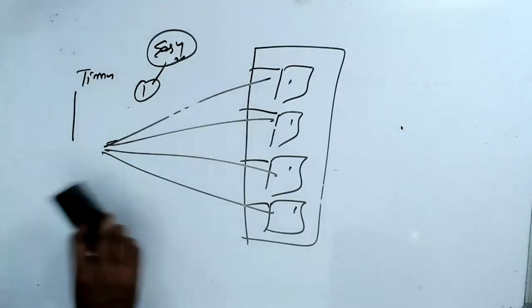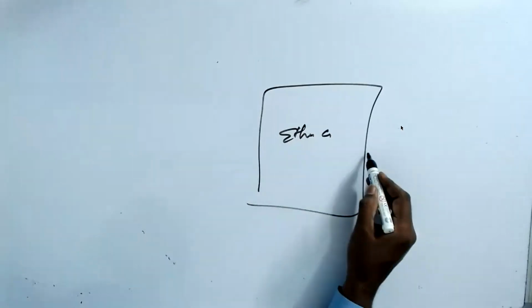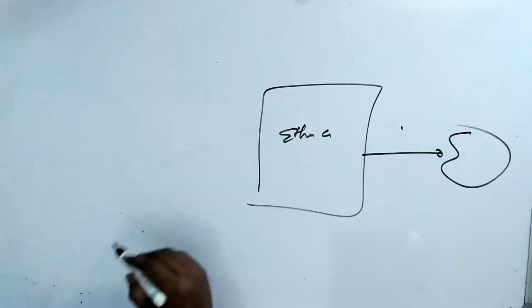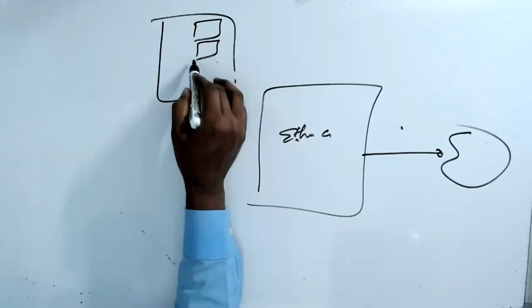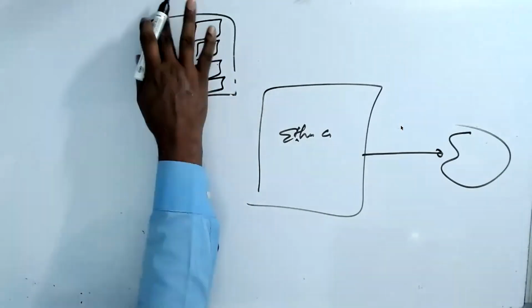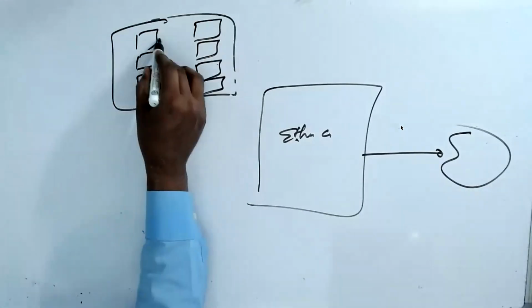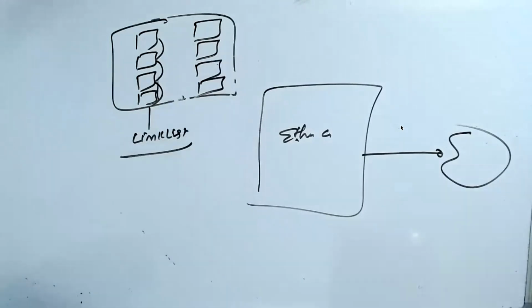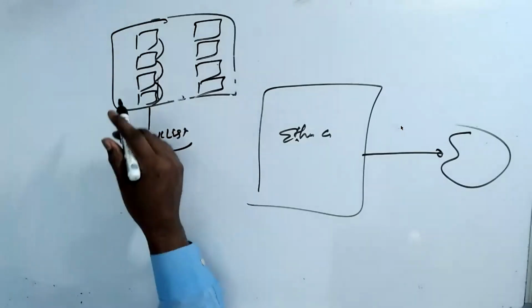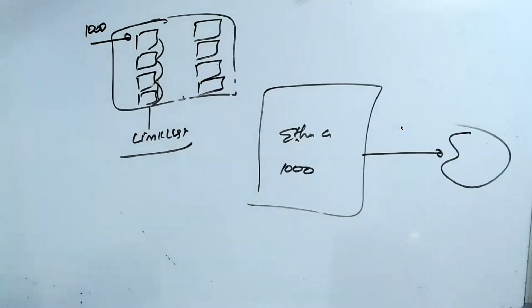The second use is, I have a controller. For example, we have taken the Ethernet controller, and the Ethernet controller sends a packet to the net. Now this guy takes the packets from memory. But where the packets are available is in the structure. This is called a linked list. But the beauty is, you create the linked list in memory and you give only the starting address to this guy. Enough. You do not have to give everything.